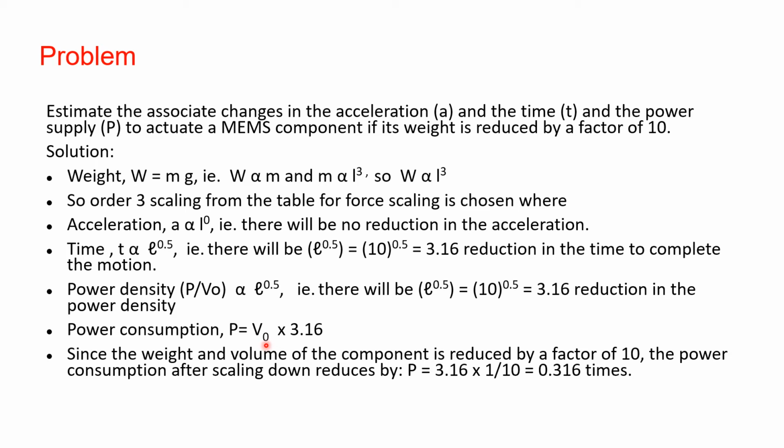V0 is the volume which reduces proportional to L cube, or it will be proportional to the weight. So the weight is reduced by 1 by 10th. So in order to obtain the power consumption after scaling down, P will be obtained as 3.16 into 1 by 10. 1 by 10 is the scaling of the volume. So this will make the power consumption reduced by 0.316 times.